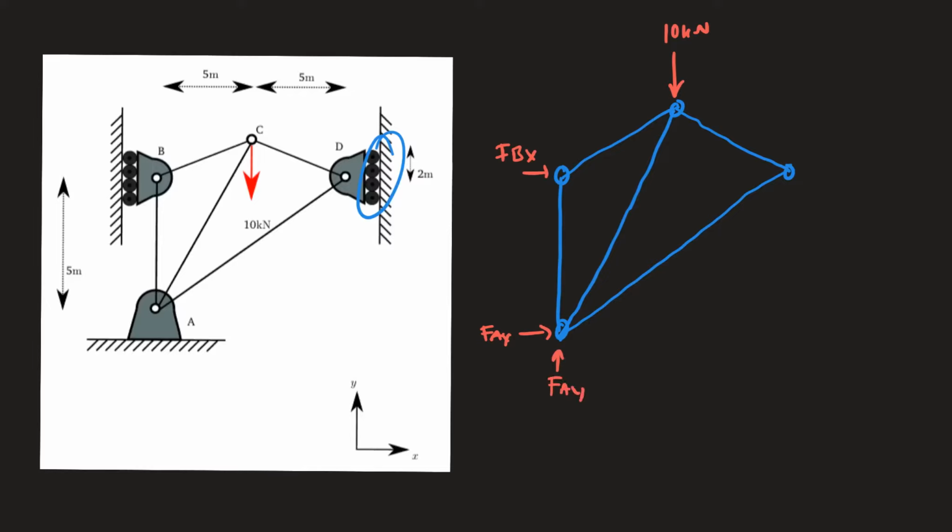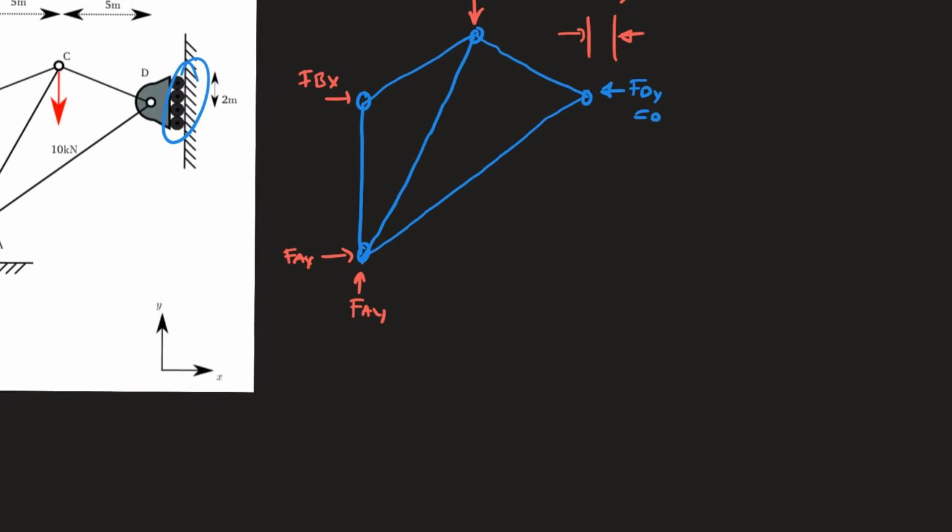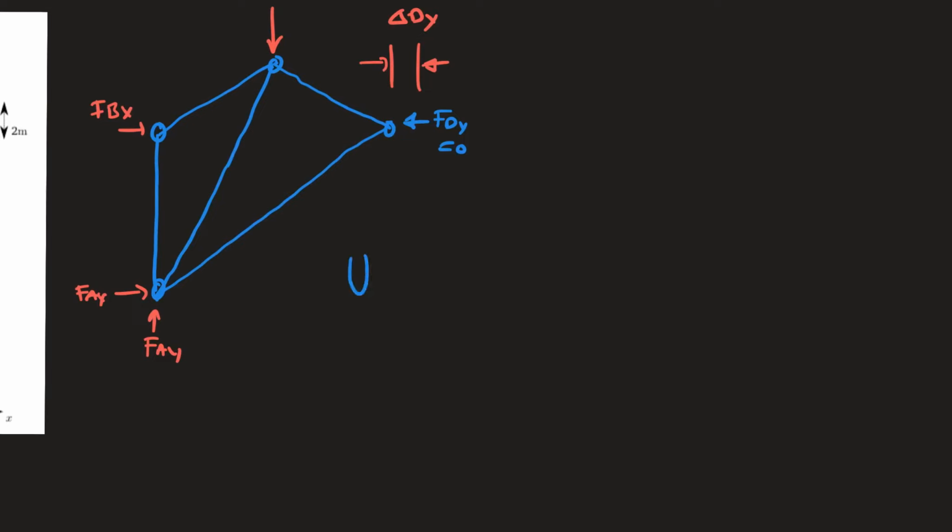And we're trying to look for the displacement. So for our unknown reaction, we're going to say that we had f dx is equal to 0. We want to look for whatever this displacement is here, which we'll call delta dx. So we look at our equation that we've just developed: the sum of UE is equal to the sum of Ui.